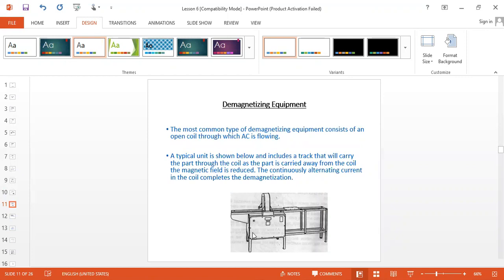So we can use both wet as well as dry methods. For example, if you are looking at in-service inspection, there are some chances of high surface cracks. So we have to use the wet method, because high surface cracks we can't detect by using dry methods. So there are limitations of this technique, and we have to use it as per procedures.